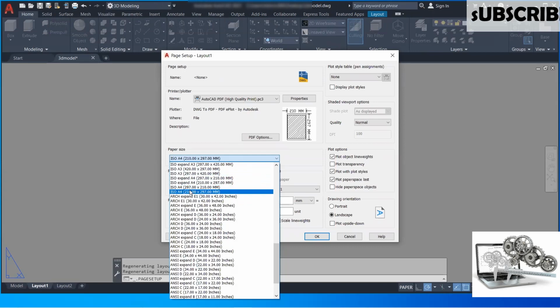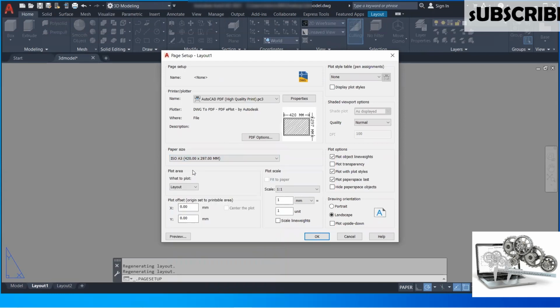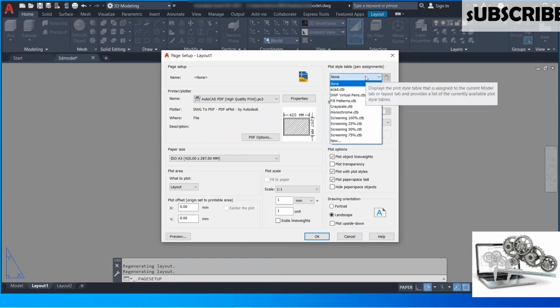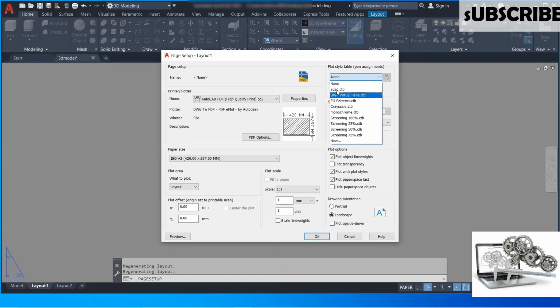After selecting the paper, that is ISO A3, we will select a plotting style. In plotting style we have different categories, that is screening 100%, screening 25%. So we can choose for color saving. Here I am going to select the default one.